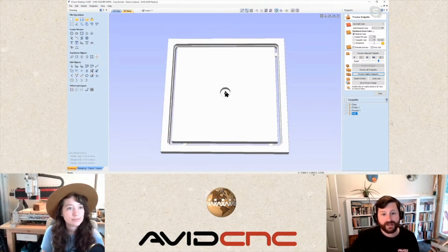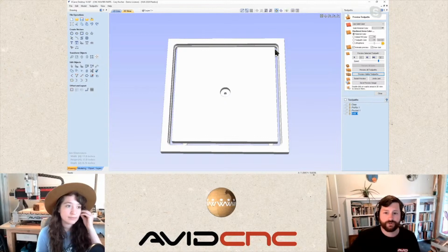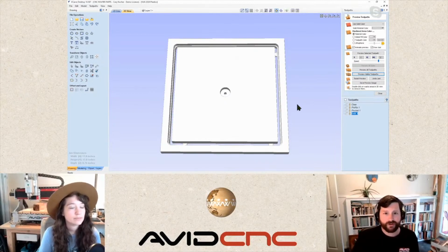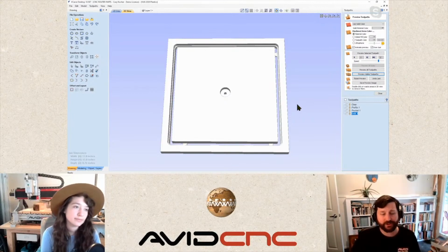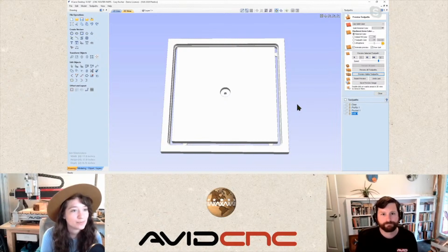Yeah, and sometimes you can add flair to your counter bores with a shape. This counter bore operation is very similar to our clearance toolpath here, in that we are essentially giving the diameter of our tool some space within the middle of our flute to get those chips up and out of the canyon we're creating, instead of having to travel all the way up the flute of the entire tool. Yeah, sometimes I do like to make the counter bore like a hex shape so that my hex bolt fits in perfectly. Yeah.